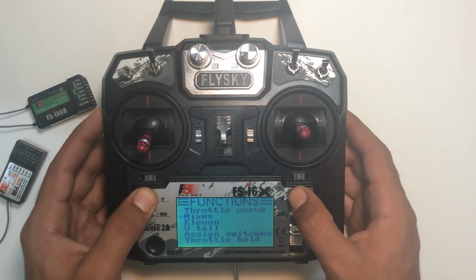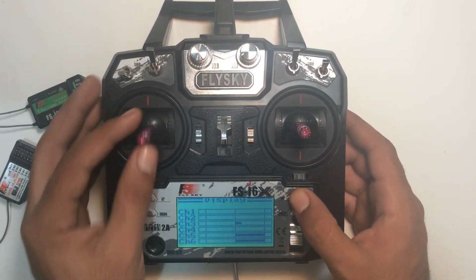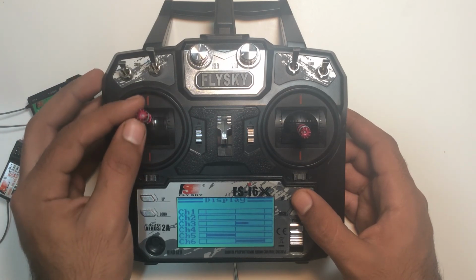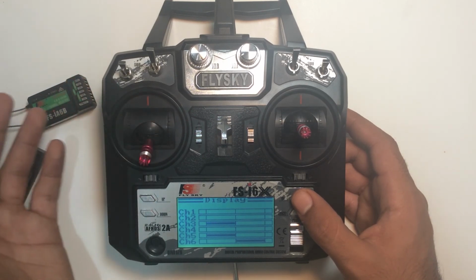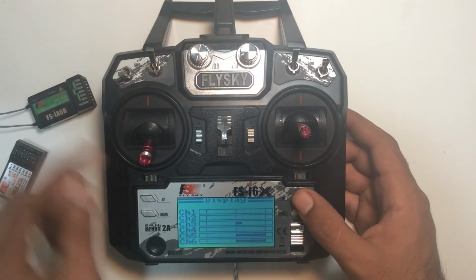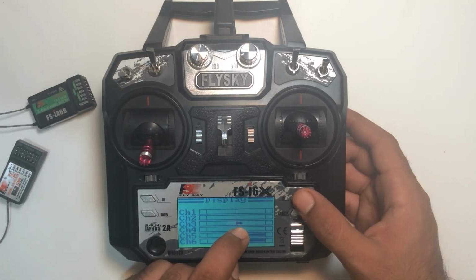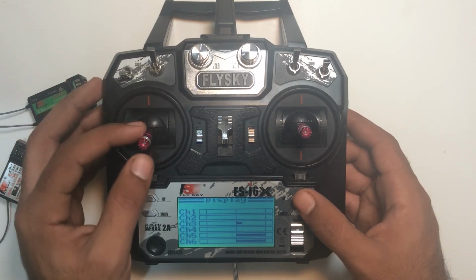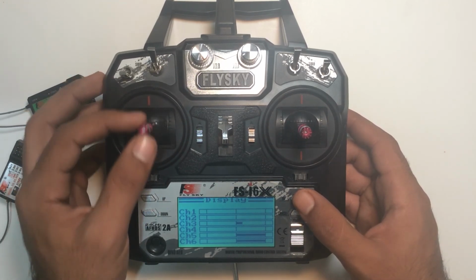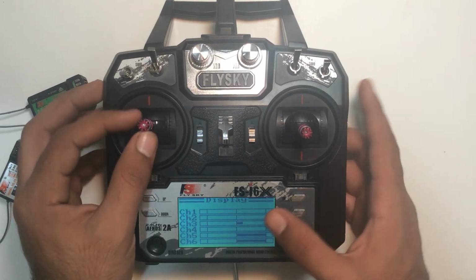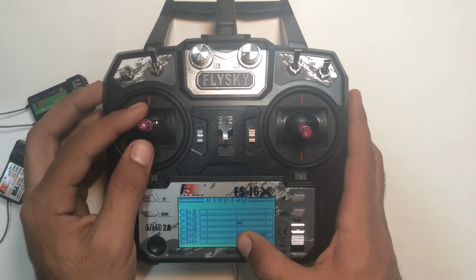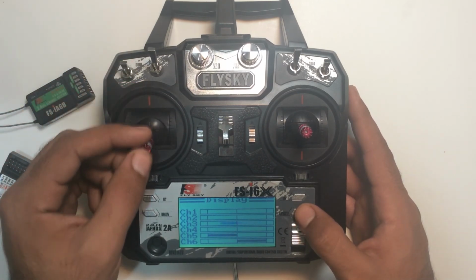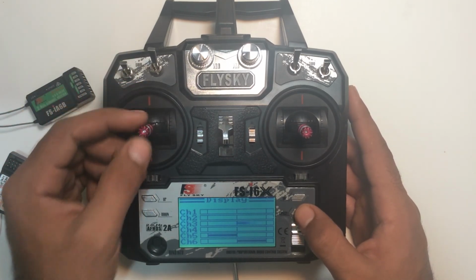So now if I go to the display settings and I want to see its functionality, upon activating the throttle hold switch, for example, my throttle is at 0 right now, and if I activate it, my throttle will automatically move to 60%. Even if I move my throttle right now, it will not move from the location we set in the settings, that is 60%. And if I just deactivate it, we can move it again.